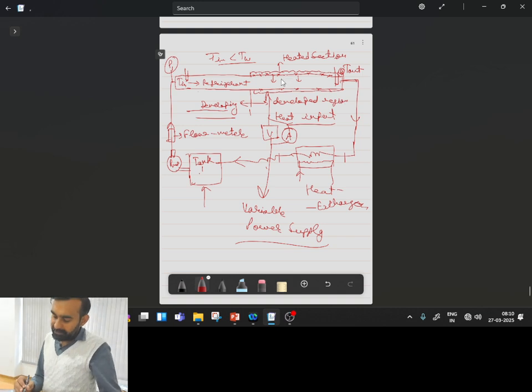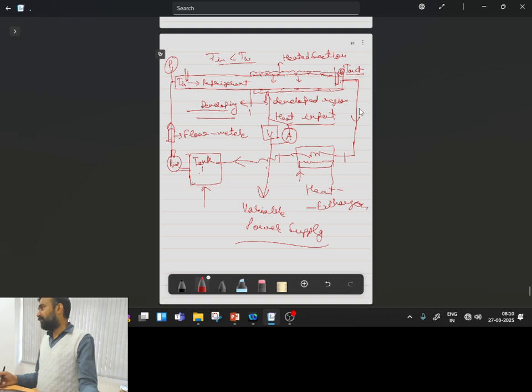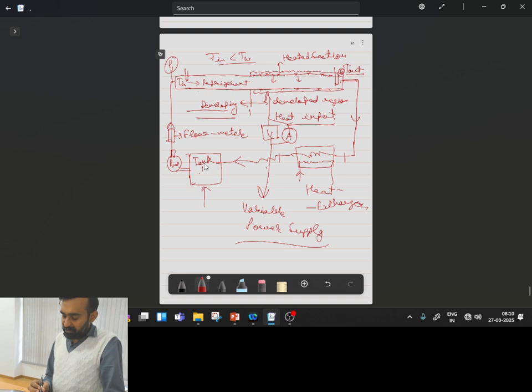For heating the tube, we were using variable power supply heaters, because if we have to vary the heat flux over a wide range, then we should be able to supply that power from the input heat source. Once the refrigerant flowing inside comes out of the heated section, its temperature will be more. But if we have to repeat this experiment for longer duration, we need to obtain the refrigerant in the tank or accumulator at the initial condition.